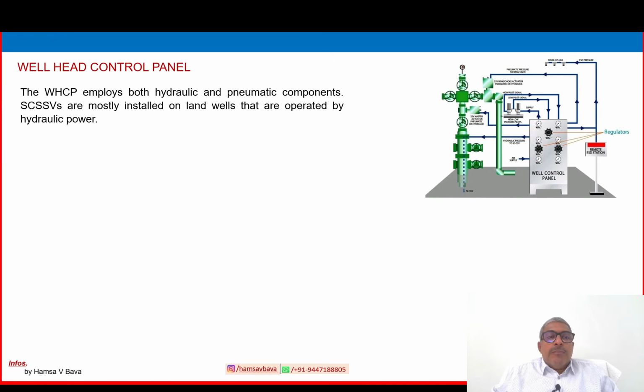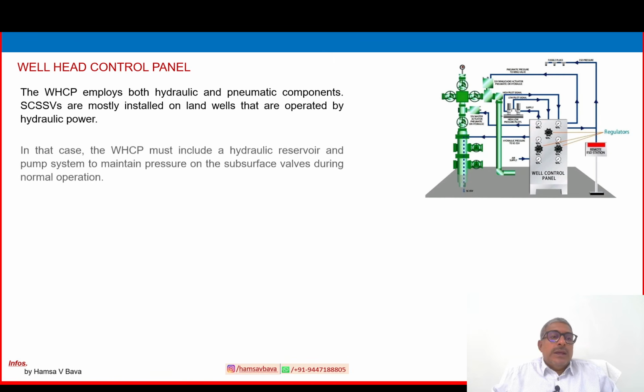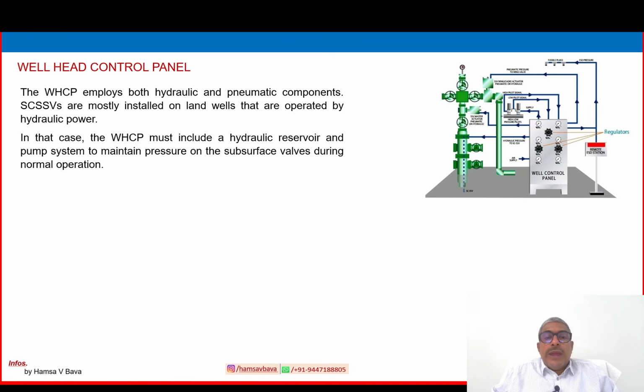The wellhead control panel employs both hydraulic and pneumatic components. Surface controlled subsurface safety valves are mostly installed on land wells and are operated by hydraulic power. So both pneumatic and hydraulic power are used in the wellhead control panel system. The wellhead control panel must include a hydraulic reservoir and a pump system to maintain pressure on the subsurface valves during normal operation.